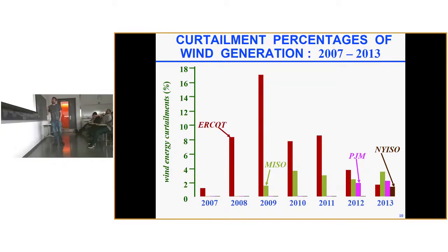And so one of the impacts of not being able to follow this net load is to simply curtail the renewables away. And you can see in 2009, ERCOT did a lot of that. The way they managed to lower this was by investing in transmission, making sure that there would be fast-acting resources that could compensate for the variability of the wind.